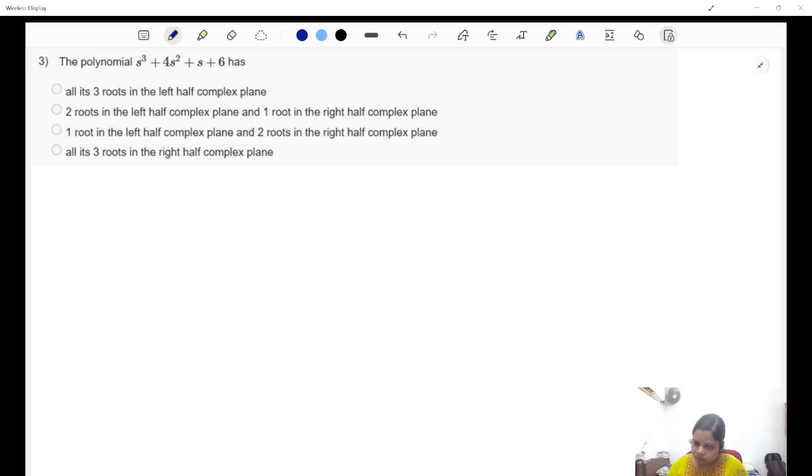Alright. So let's construct Routh's array, because here n is greater than or equal to 3. The very first thing is we have to check the first two conditions. Both of them are satisfied, right? We don't have any missing powers of s over here, which means all of them are non-zero. The second thing is all of them already have the same sign. I think the necessary condition is satisfied, which was having both those things, and for sufficiency we need to go for the other ones. Okay, let's construct the Routh's array.